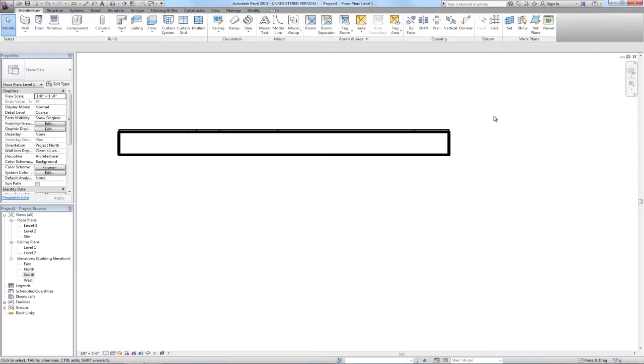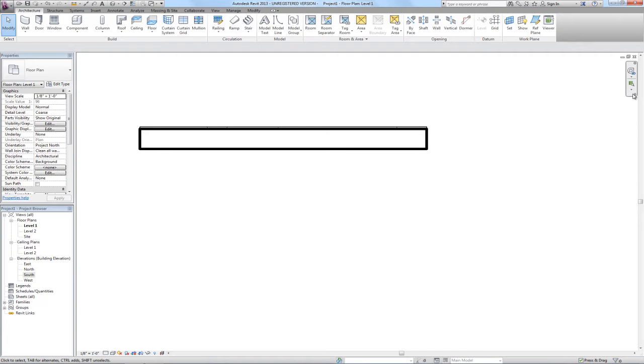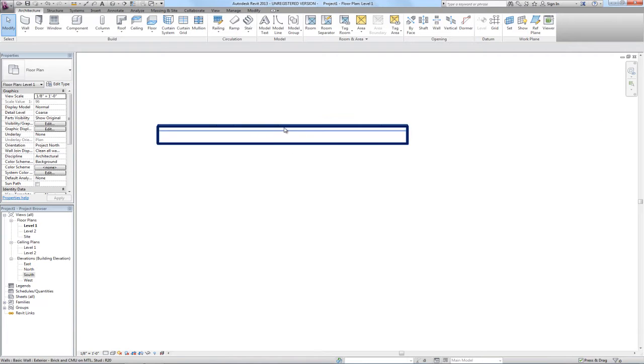We also have a couple of zoom features over here. Let me just zoom in real quick. If we click this down arrow, we see that there's zoom region. Notice that was a split button, so clicking the top part of the button would have done this top default command, which is zoom region or zoom a window that you select. We also have the ability to zoom previous. So if I click that, that zooms me out to whatever my previous view state was.